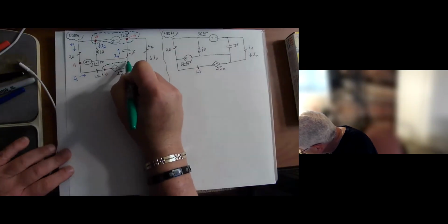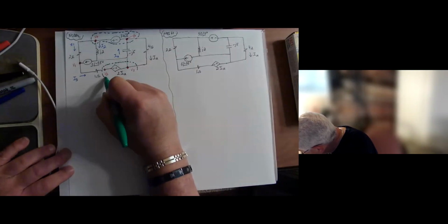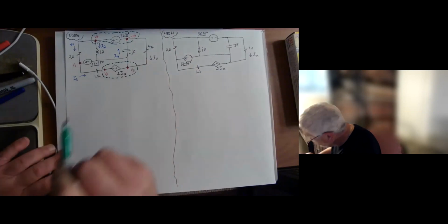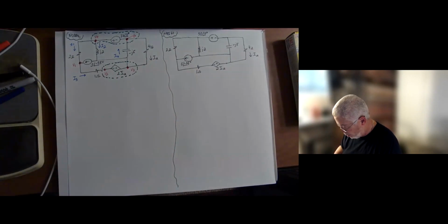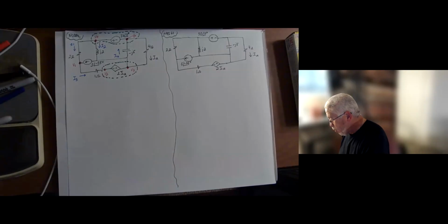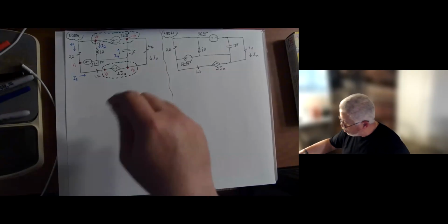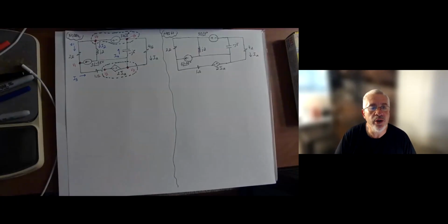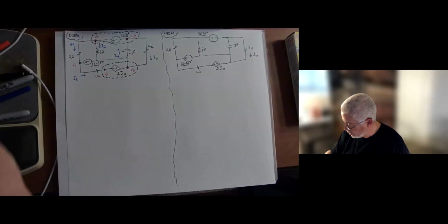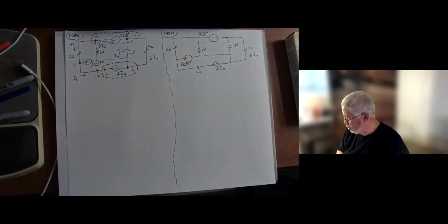It's a dependent voltage source that depends on the current, but it's a voltage source by virtue of the plus minus in the diamond symbol. Okay, so we draw the supernode here. Of course, later on we're going to discuss when we do KCL about the supernode and when we do not, but not at this point. Okay, but the circuit is prepared for solution.